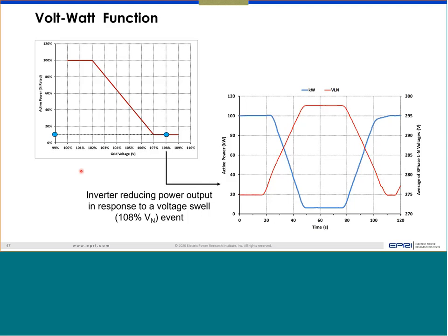A few other things had to be adjusted, and then it was able to operate at night and provide reactive power support. It's a transmission-connected system, and we have tested up to 30 MVAR during nighttime without any solar, of course. So theoretically it's possible if it's designed for that purpose; you have to ask for it, saying that you need reactive power support during nighttime. So it has to be designed or configured for that.